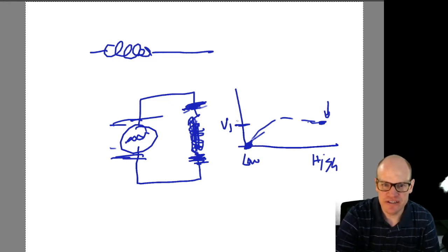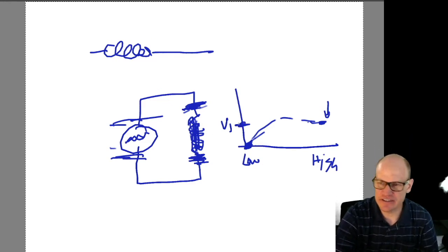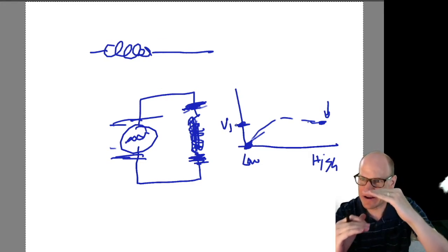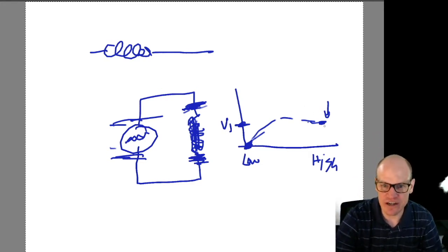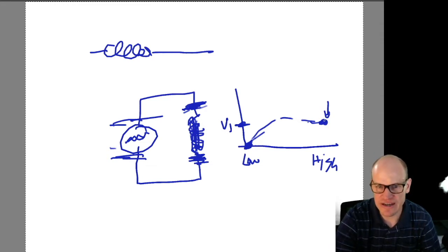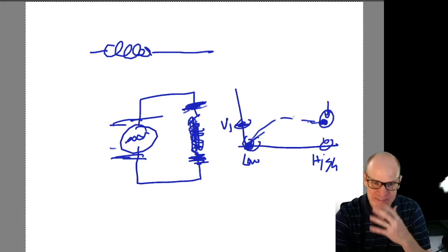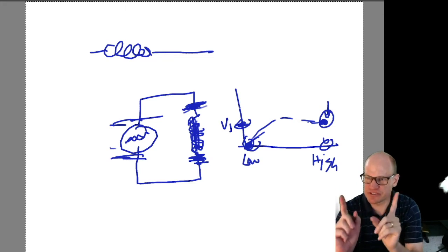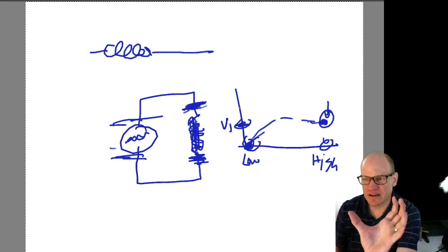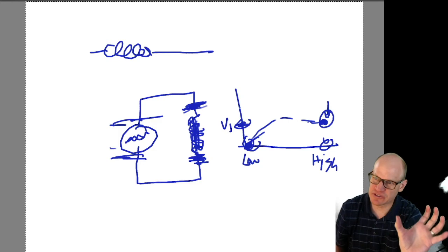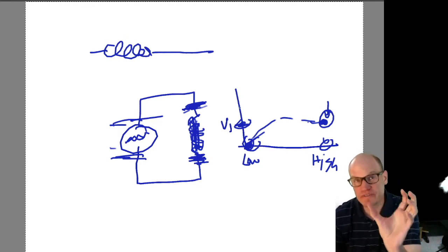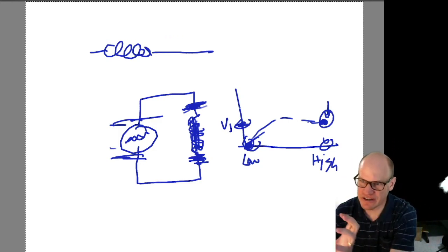The capacitor at low frequency acts like an open in the circuit, like no current can flow at all through the capacitor. Where an inductor, that same situation applies, where there's no current that flows through the inductor at high frequencies. So the capacitor has this response for low frequencies. The inductor has this response at low frequencies, where the capacitor has that response at high frequencies. So they behave exactly opposite each other. One of them resists low frequency oscillations. The other one resists high frequency oscillations.